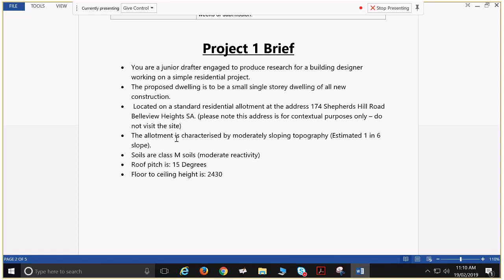If we're building an 8 metre wide house and we need a metre either side of that house, we've got to be cutting into that earth probably about 1.5 metres. We're going to have to retain 1.5 metres of soil on one side from where we cut in. So I give you those things to think about. In that situation, is it good for a raft slab where we have to cut into the soil, or should we have a suspended floor where we're up on stilts, we don't have to do any disturbance of that soil? So I'm giving you this context.